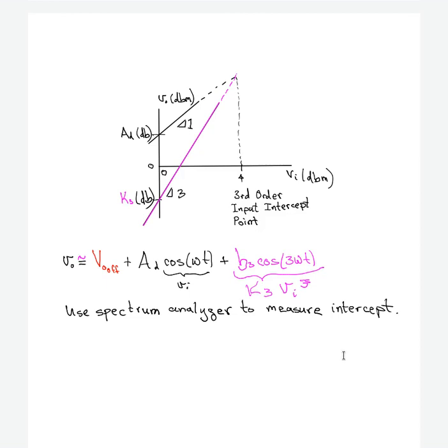Well, if you make a plot of Vin versus Vout here in a logarithmic fashion, I'm plotting Vin in dB relative to a milliwatt. So dB is a logarithmic thing, and dB relative to a milliwatt is how many dB a thing is greater than a milliwatt. Like, say, 0 dBm would be 1 milliwatt. 20 dBm would be 100 milliwatts. Minus 20 dBm would be 1/100th of a milliwatt. So that's how the x-axis is plotted.